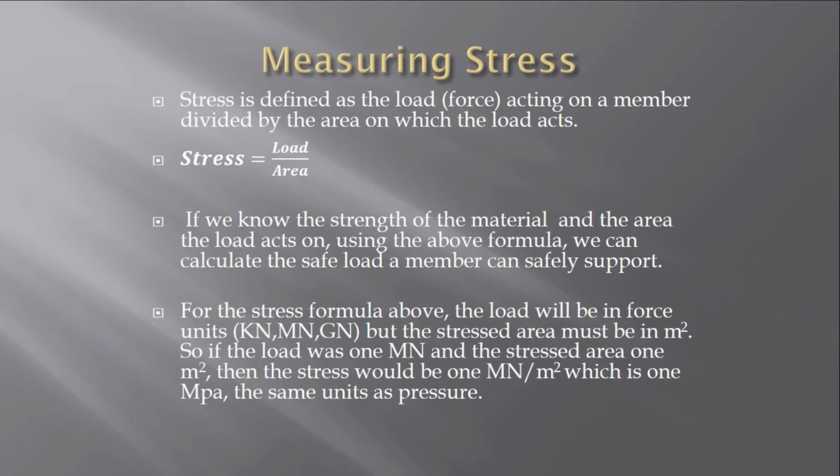Stress is defined as the load acting on the member divided by the area on which the load acts. If we know the strength of the material and the area the load acts on, using the above formula we can calculate the safe load a member can safely support.